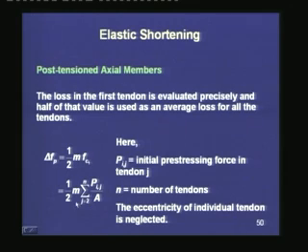To summarize, delta Fp is equal to half times the modular ratio times the summation of the prestressing force in each tendon divided by the area of the cross section, and this summation is done from 2 to the total number of tendons.